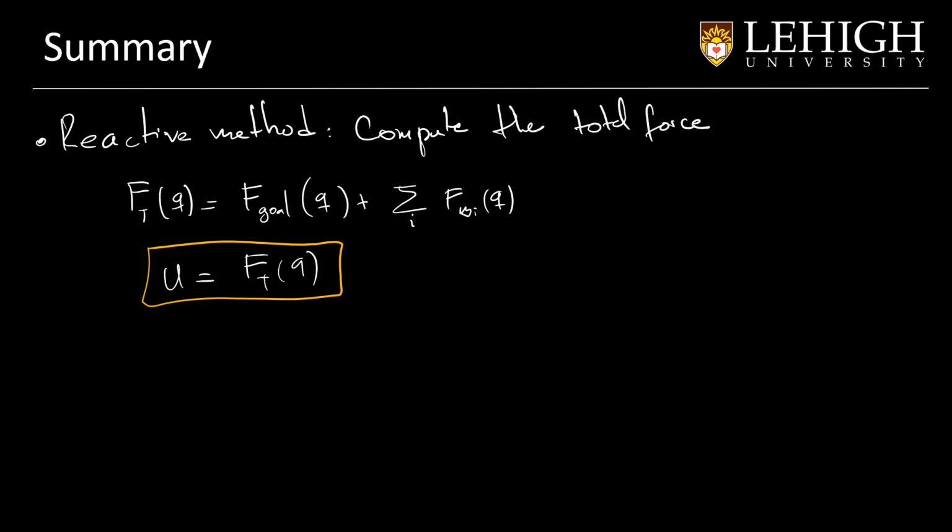If we see, the computation of this equation is pretty simple because it only depends on the number of obstacles. And even if we have many obstacles, the force that the obstacles generate when they are very far is very low. So we can even reduce the complexity by only checking the obstacles that are close to the robot, so we don't need to have problems with the computation.